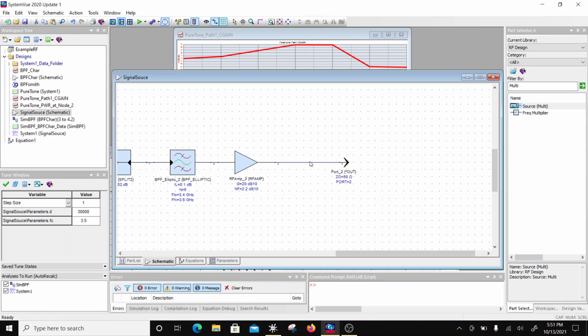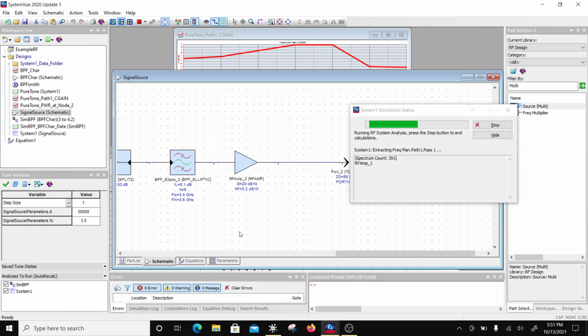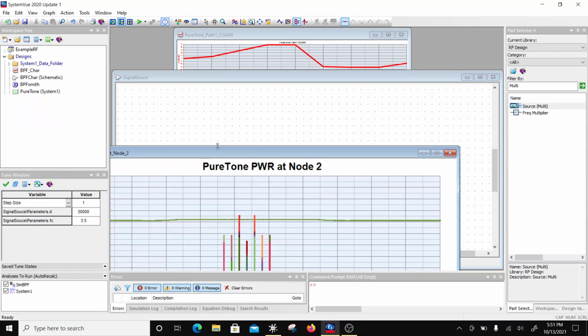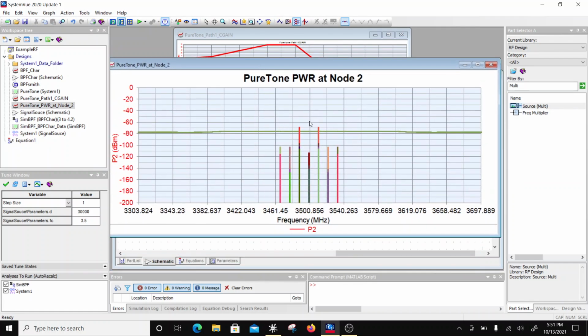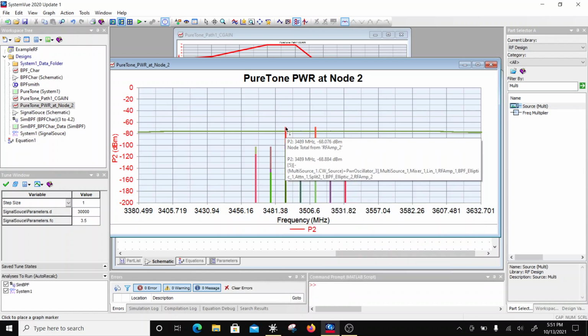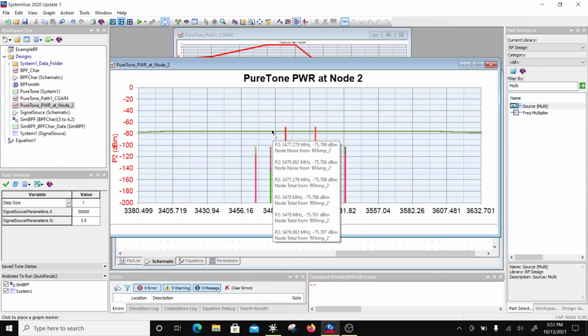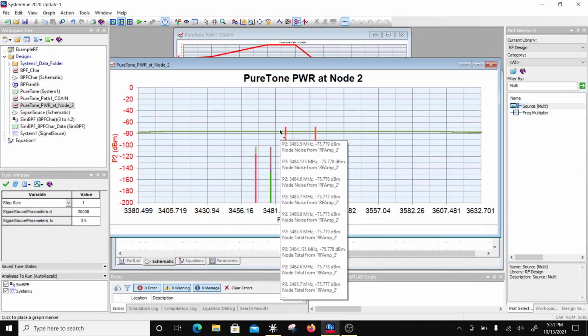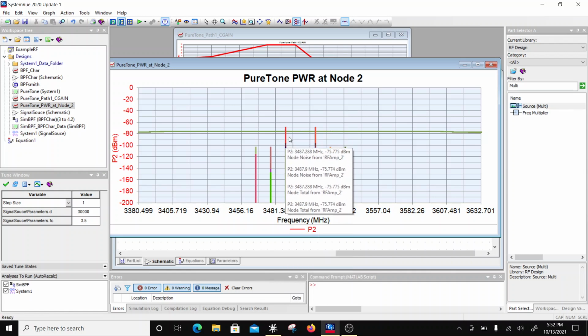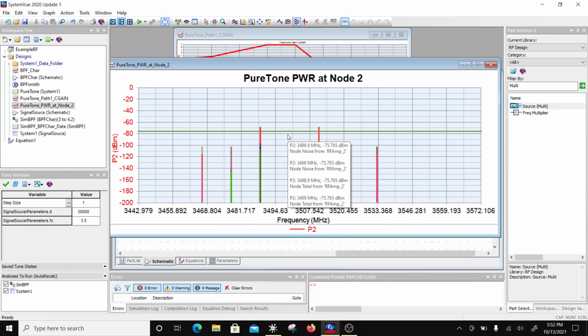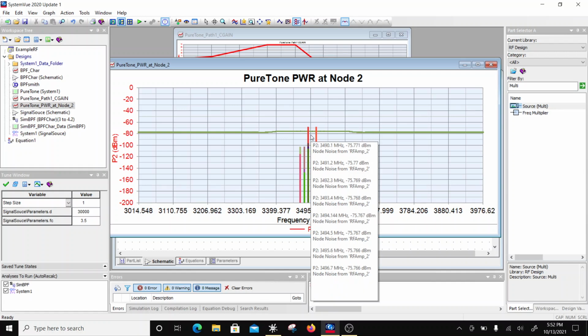Next, let's see what happens to the curves here. Of course, this is the worst case scenario. So this power is minus 68, and this power is 75.7, 76. 68 to 76 is again 8 dB. So signal to noise ratio is still 8 dB in my band, right?